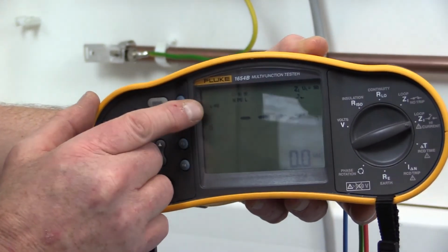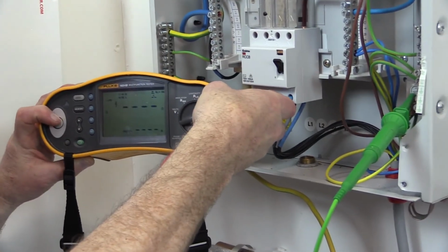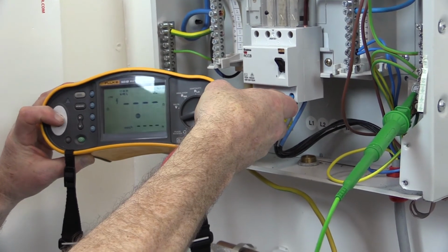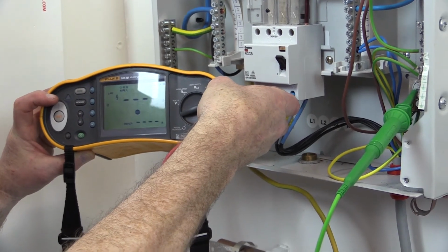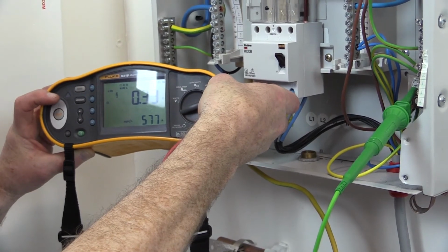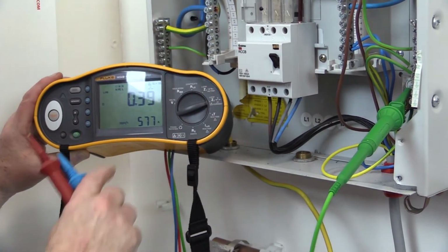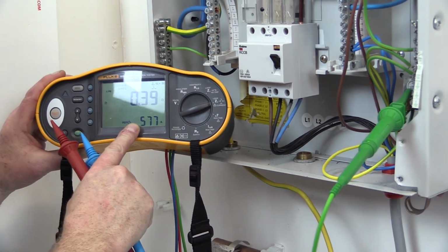Using the 3 lead test probes, we then connect the earth test lead using a crocodile clip to the main earth terminal. Now please note, it's not necessary to disconnect the earthing conductor during this test as we did earlier when testing the earth fault loop impedance external to the installation. We then apply the second probe, which is fused, to the neutral conductor, and the remaining probe is applied to the line conductor L1. We press the test button and the earth fault loop impedance is displayed together with the prospective earth fault current, which is seen at the bottom of the display screen in amps.